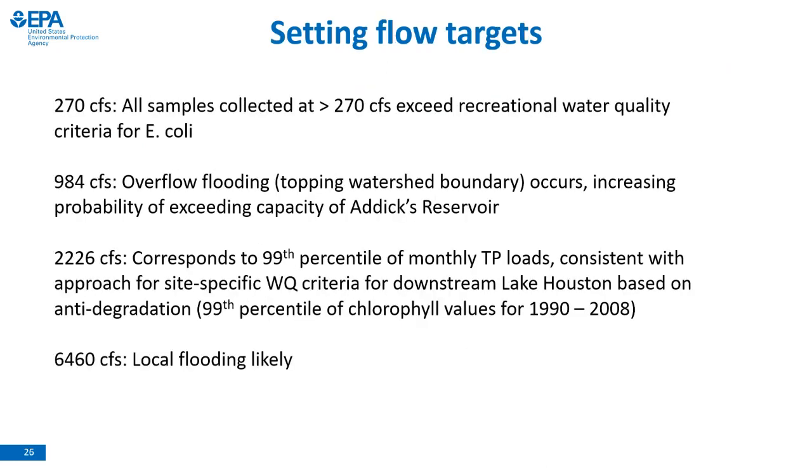One of the things you can do in WMOST is evaluate the synergies between managing flow, peak flows, or low flows for that matter, and meeting water quality targets. So we actually set up a series of flow targets to try to meet with analysis with WMOST. So at the high end, above discharge levels of 6,400 cubic feet per second, we want to avoid exceeding that target because beyond that, there's likely to be local flooding damage within the watershed.